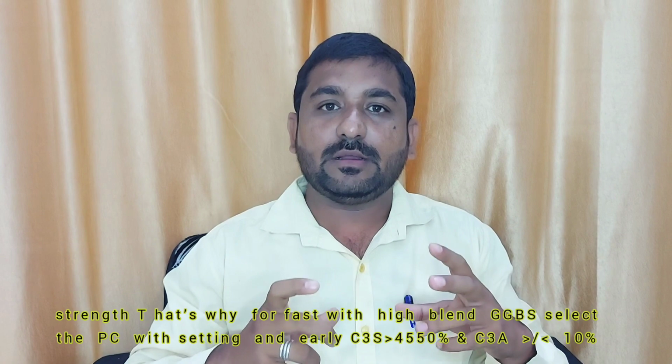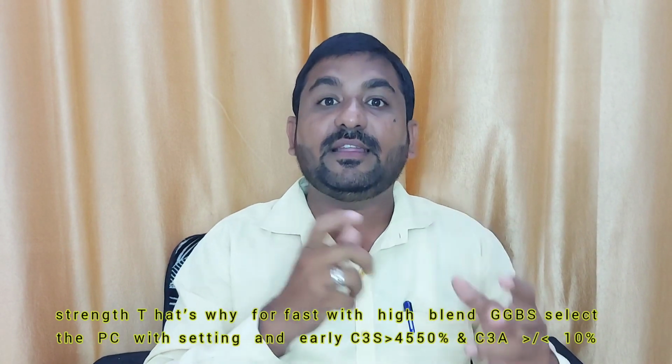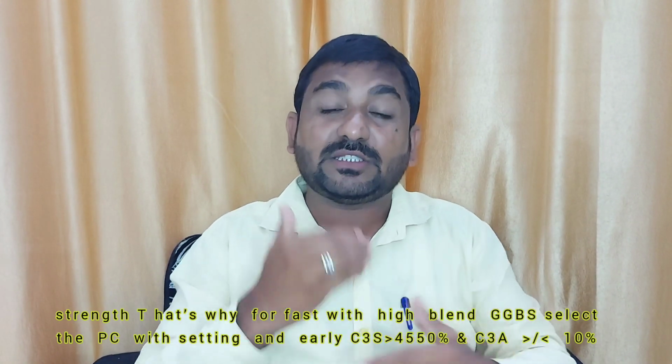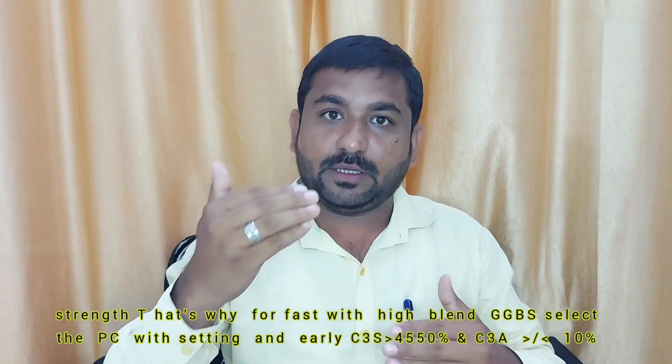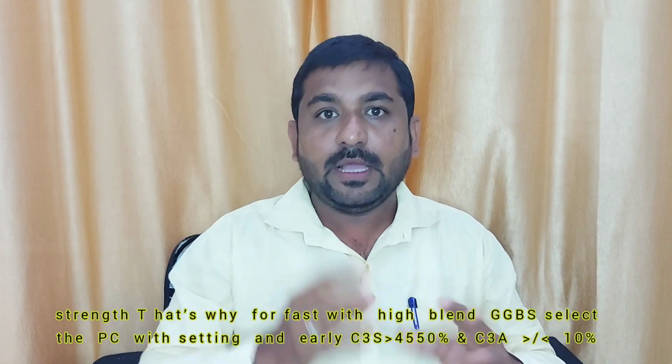The second criterion, you will not get in the market exactly what you are expecting, but you will get the second option like C3S, which is also present in the cement and which also enhances the setting time and the strength gaining properties of the hydraulic cement, or the OPC 53 or 43 grade of cement. So at the time of high replacement of GGBS, you have to select the cement in which the share of C3S must be more than 45%. If it is 50 or 55%, then we can go.